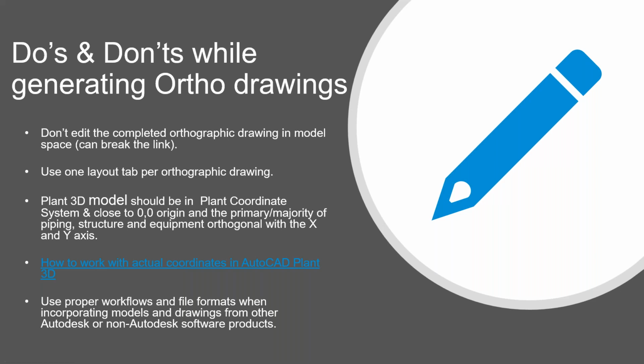Mayor Weiss had asked if you want to add some 2D objects to the view, for example, column grids or hatch lines. Yes, you can get away with that by throwing that into model space, but just be aware, it may delete them, so have that geometry handy. When you regenerate the view, it may clear out that model space of those entities, so your column lines or hatch lines or whatever. But they should also be okay to put in the 3D model. And when you're generating the ortho view, they'll come through fine. They won't get hidden out. But if you do need to add something into the ortho view, I've seen people do it. It's not a recommended practice, but it doesn't break anything.